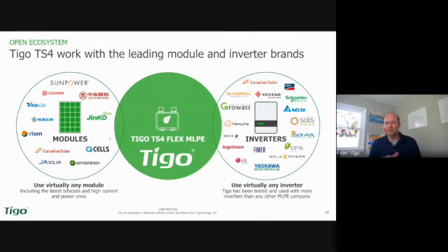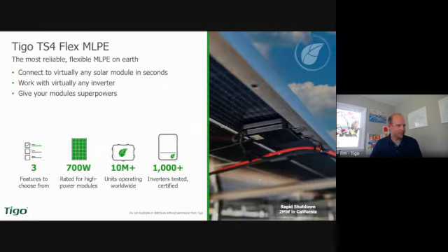We do have resources on our website. There's a Tigo inverter compatibility tool. So if a customer says, hey, I want to use a Solis make and model inverter, you can look, find it, and make sure it's compatible. Chances are it is, but you can always confirm that through our tools and resources.